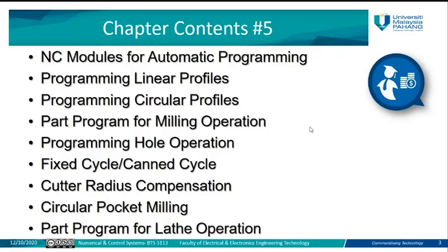Then programming of circular profiles, which we mentioned before, for example G2, G3, clockwise, counterclockwise. We are going to use this as a complete profile to conduct CNC milling. Then we are going to talk about part programming for milling operations, and programming hole operations for drilling.